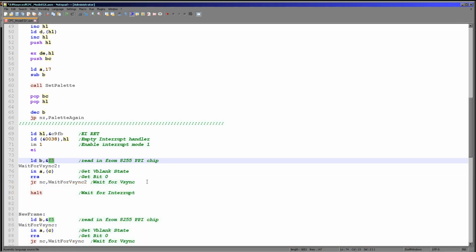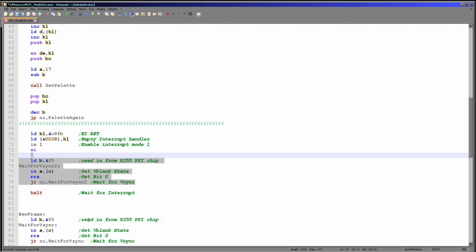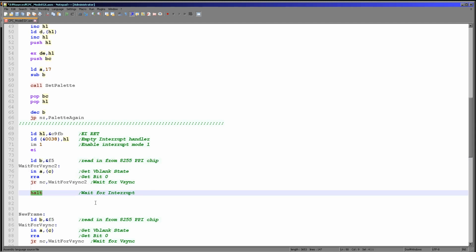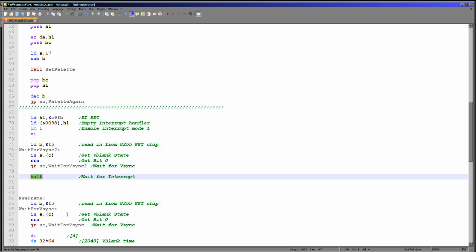So what I'm doing is I'm waiting for VSync, and then waiting for another interrupt, and so we'll now be 1/6 of the way down the screen, and at this point we know we're not in the first VSync. We know we're at a very, very precise time because we've waited for that interrupt, and now we can really start to work with very precise timing here.